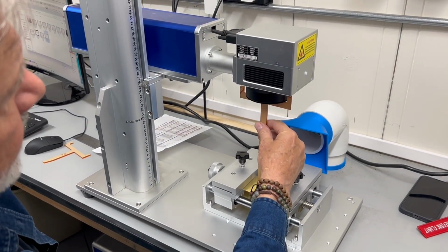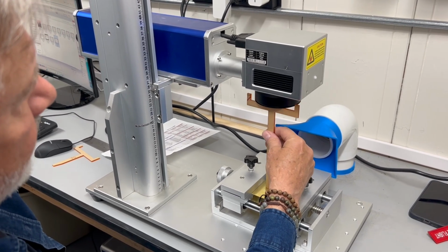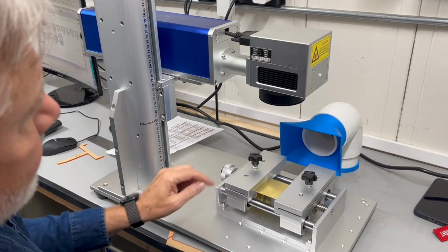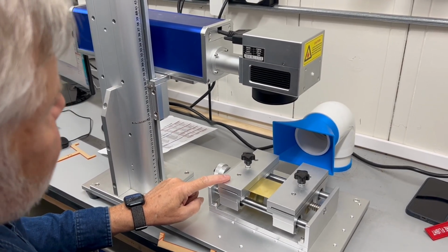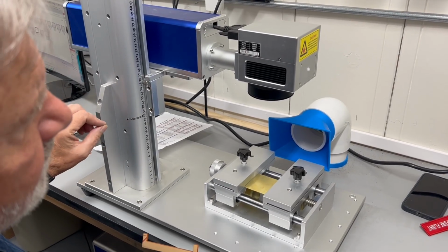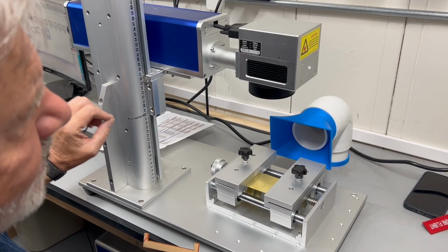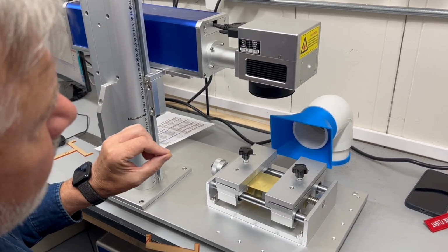You just move it down like that. Just make sure that it kind of slides in, a lot like the CO2 laser. That means that you have the absolute best focal distance. The reason that you want that focal distance is because the library that we provide for you, all of the settings for the materials, for engraving and cutting, have assumed that your laser is at the optimum focal distance.